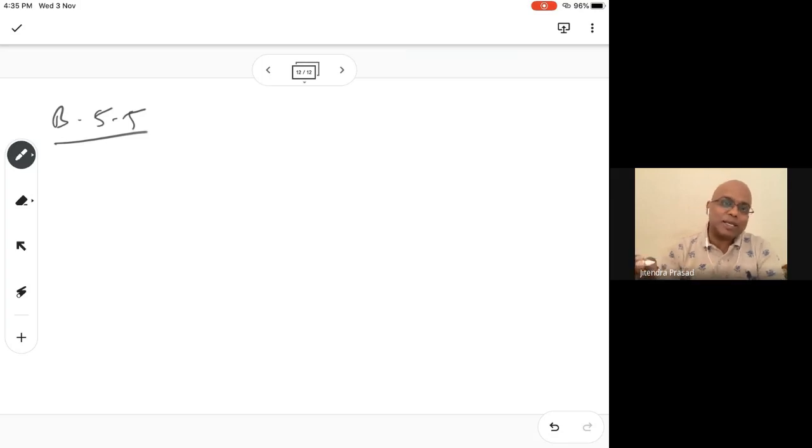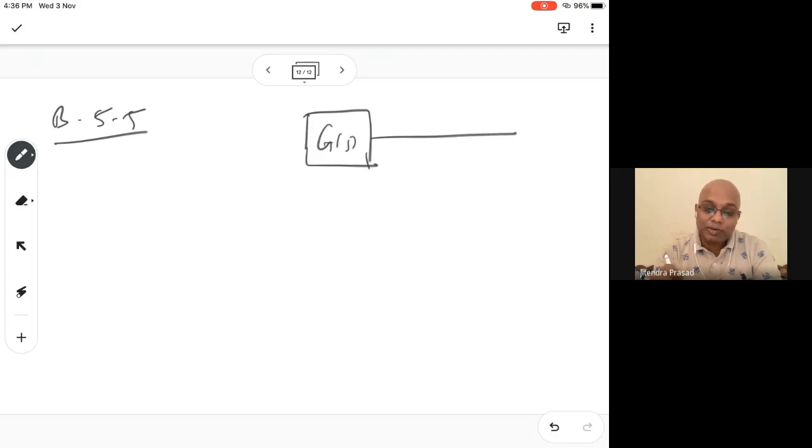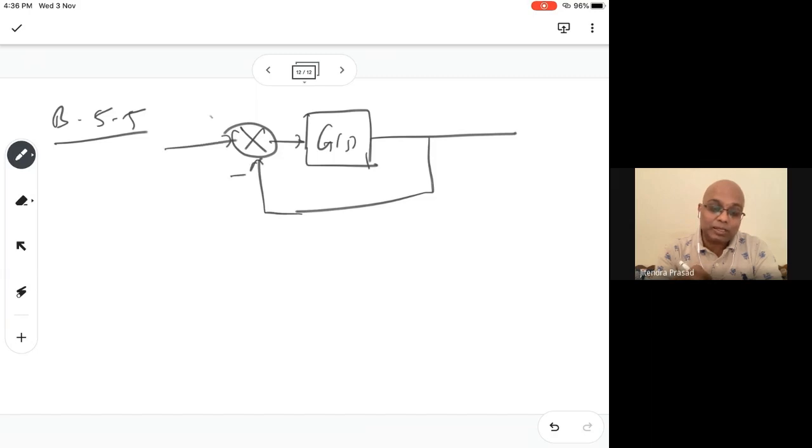This is easy. Whenever an open loop transfer function is given, and it is written that it is a unity feedback loop, you always have to make the closed loop system first. So you have the G(s) here, and you know it has a feedback loop, going like this, minus, this is plus. First we find the closed loop, always find the closed loop.